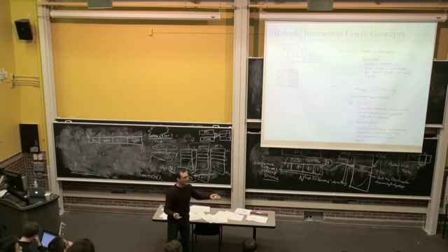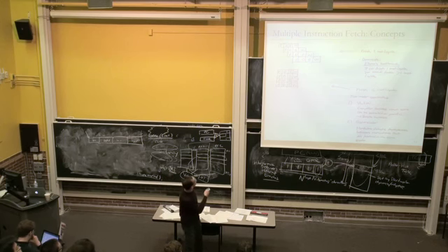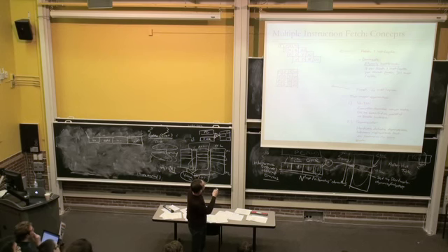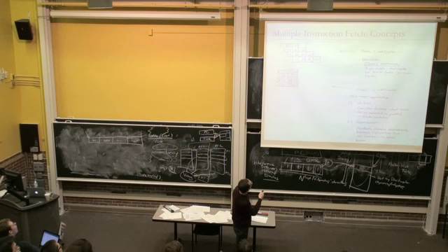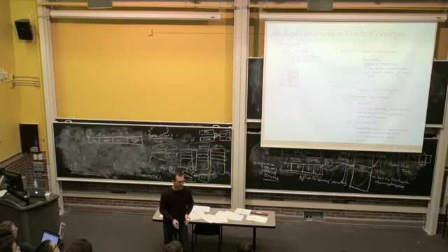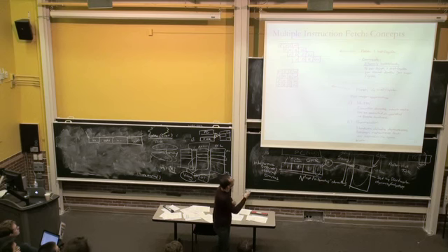What is a superscalar processor? We're really doing multiple instruction fetch with a superscalar processor. This is the cartoon that I drew for a pipelined processor. You're fetching 1 instruction per cycle: fetch, decode, execute, write back. The next instruction is fetched after the fetch of the previous instruction is complete. The downside is if you fetch only 1 instruction per cycle, you can only retire 1 instruction per cycle. Your throughput can be only 1 instruction per cycle. That's called the Flynn's bottleneck.